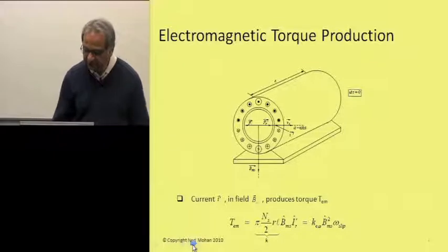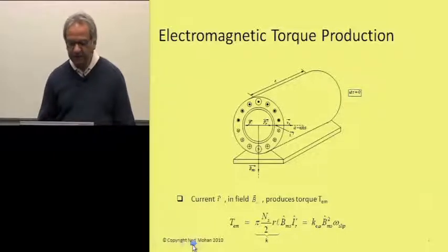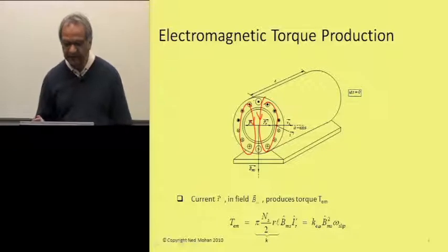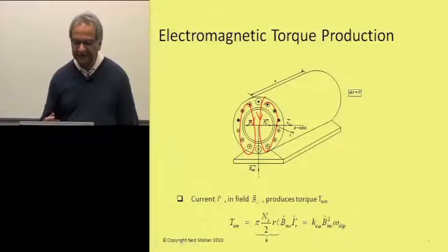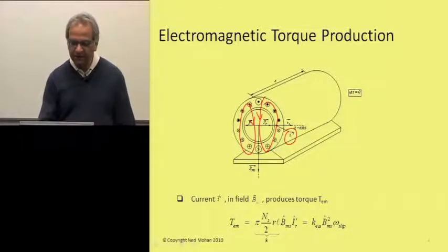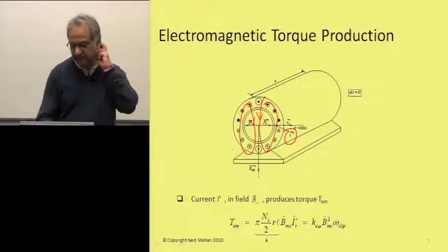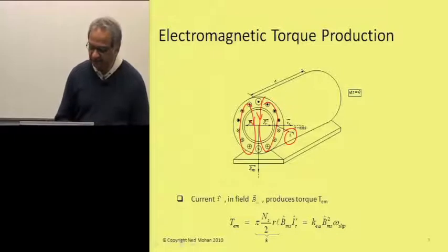And we can also calculate the torque, because we have this magnetizing flux that was produced here. Then to nullify the rotor MMF, this I_R prime space vector is drawn, which can be represented physically through a hypothetical winding.